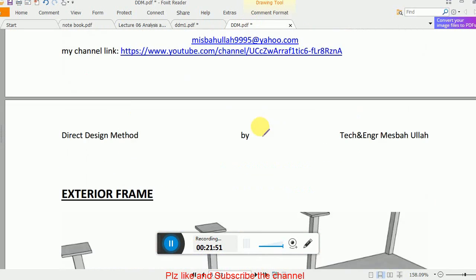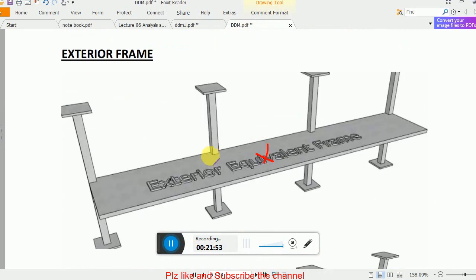Okay, in the exterior panel you have to remember that once you divide the 20 divided by 2, from the center of that column to this edge. Remember, this is 20 divided by 2. And the column strip width is basically from the far edge of the slab to that one. So this is your column strip width, and you have to add up that half.